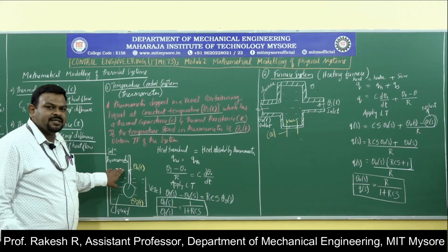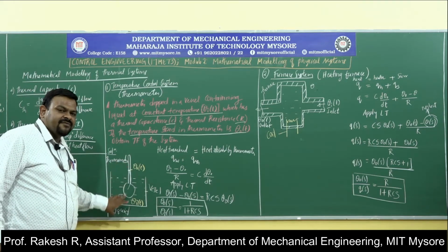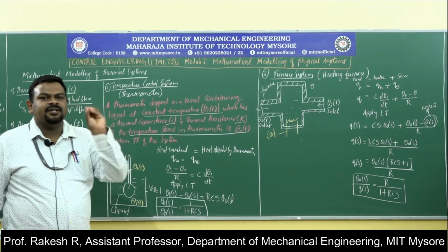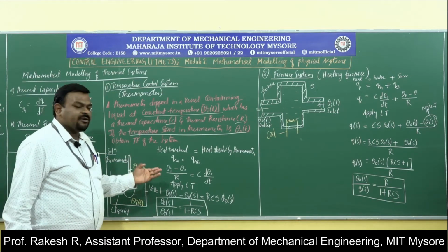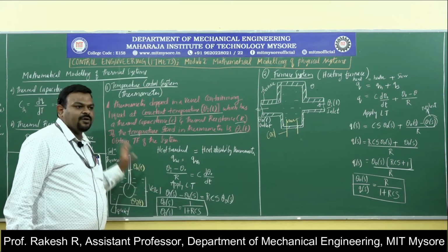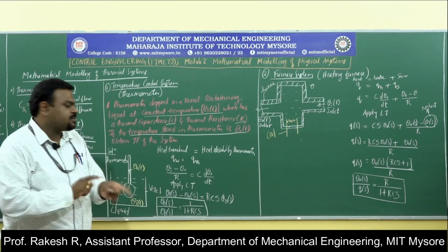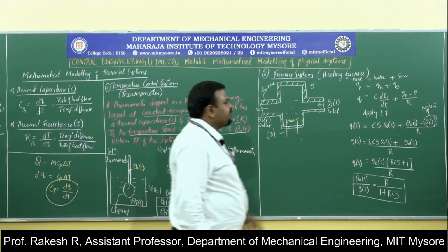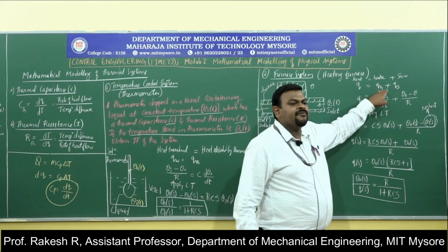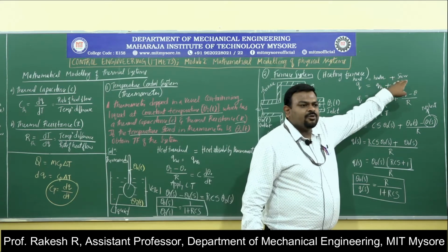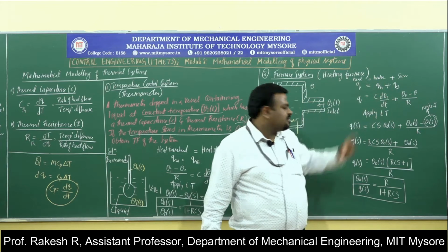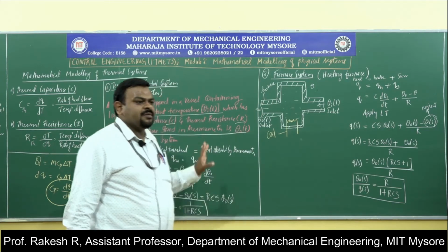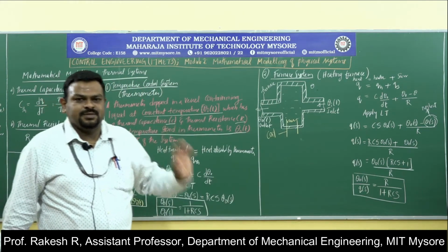Basically, the thermometer is dipped in a vessel containing a liquid at temperature theta 1, and the thermometer has temperature theta naught. So what is the heat transfer here? Heat transfer by the water bath equals heat transfer to the thermometer. Just substitute the value of Q and you will get the equation. Here also, write the law of conservation of energy equation, substitute the heat transferred through the water and through the surroundings, then apply the Laplace transformation, and you will get the answer. This is about modeling of thermal systems. Thank you.